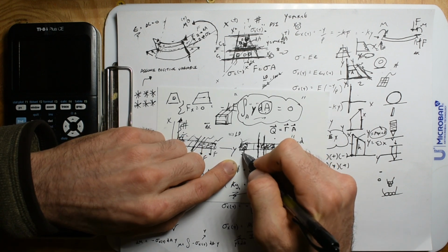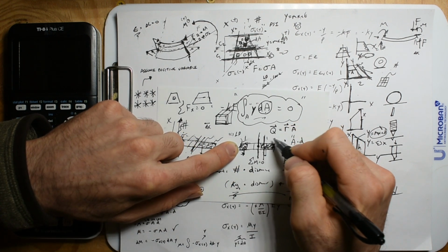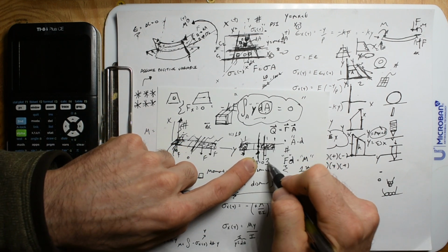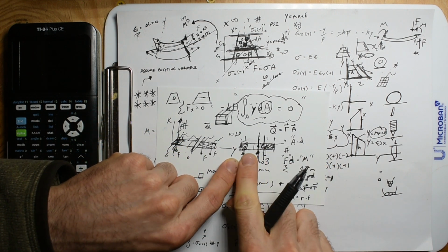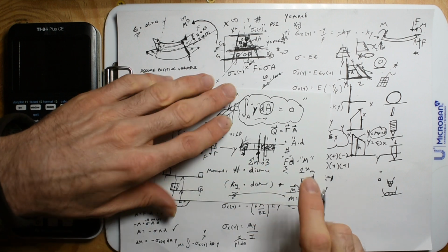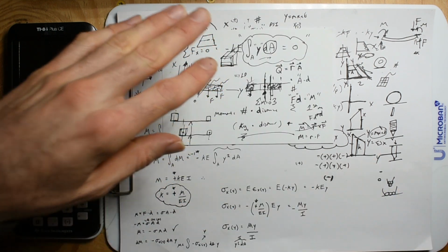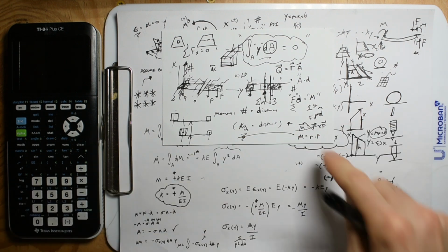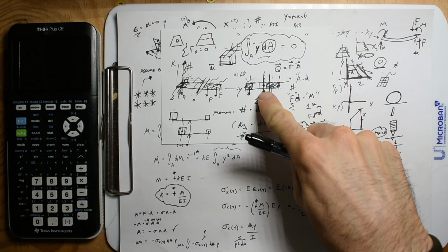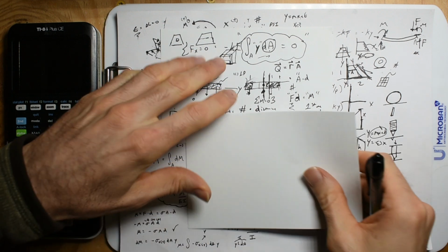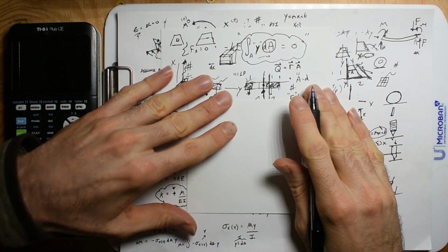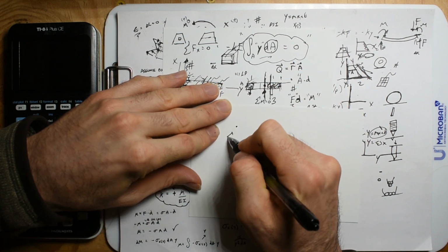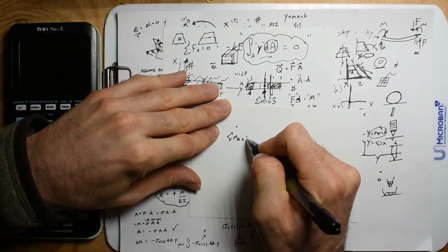If I have 1 pound down, 1 pound down, 1 pound down, and then balancing it is actually supporting it, so I'm going to have 3 pounds up where I balance this. And then some of the forces can be in any direction you want them to. If there's no external torque at that center, there's no torque anywhere. So I'm going to call it point A. I could say the sum of the moments about A is 0.